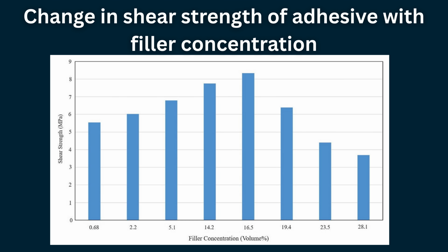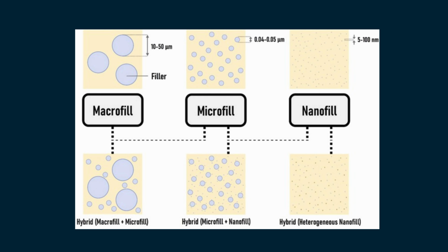Filler loading. Adhesives generally contain low filler content. Excess filler increases viscosity and reduces surface wettability, limiting penetration into the etched tooth substrate. High viscosity may also interfere with polymerization kinetics and decrease the degree of curing. Therefore, an optimal balance between reinforcement and flow properties must be maintained. Additionally, the colloidal stability of filler particles in the adhesive formulation is crucial to prevent sedimentation and ensure homogeneous dispersion.